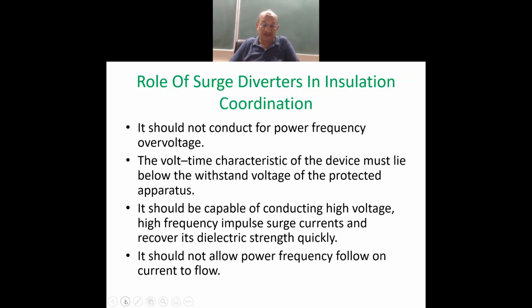We have also learned the role of surge diverters in our network. We have already gone into detail. Now, the surge diverters, as I said, have a characteristic that they do not let pass the power frequency voltage, and the volt-time characteristic of the device must be below the withstand voltage of the protected apparatus.